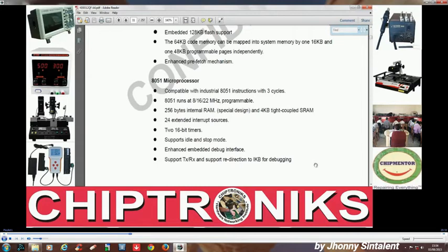You can also repair. There are 4 major ICs present on a notebook motherboard. You can try replacing those 4 major ICs. You can try reflashing. You can try changing the power controller, and you can repair at least 60 to 70% of boards. But it will take you time, and it will take you cost. So we are going into such details, and we're using these concepts also.